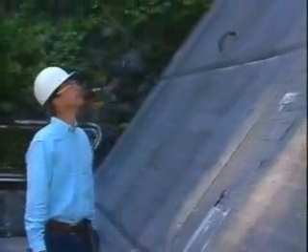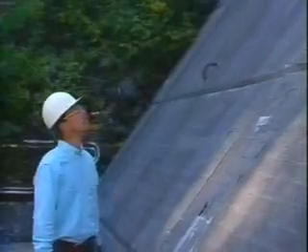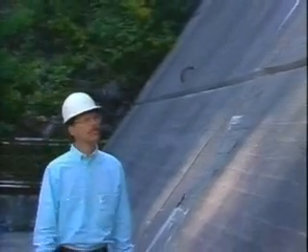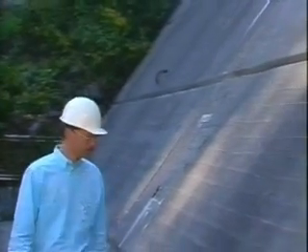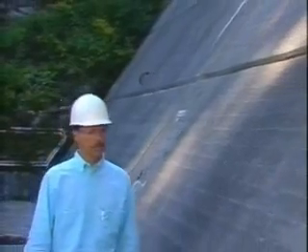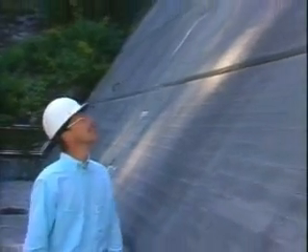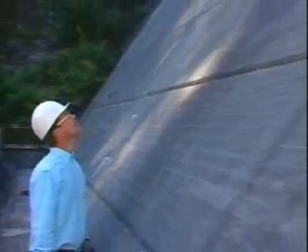After you have scanned the downstream face of the dam from a distance, you may decide to make a closer inspection of certain areas of concern. You may be able to do this by walking along the abutment contacts and the toe. In some cases, where tailwater at the toe of the dam prevents access, it may be necessary to continue the examination from a boat.